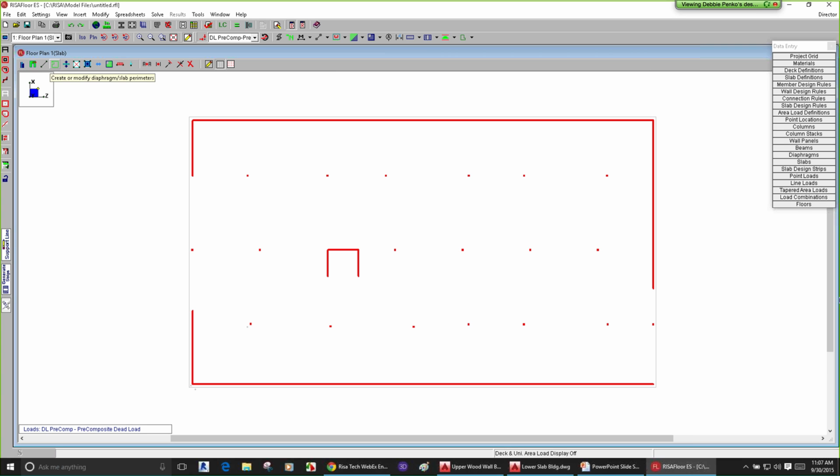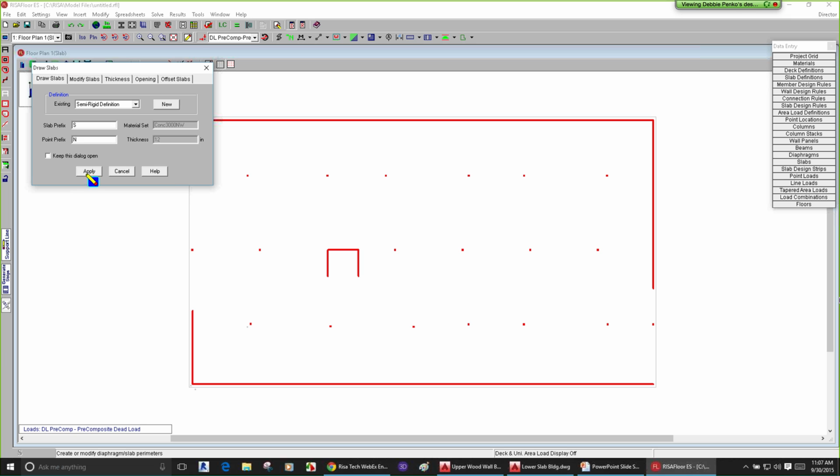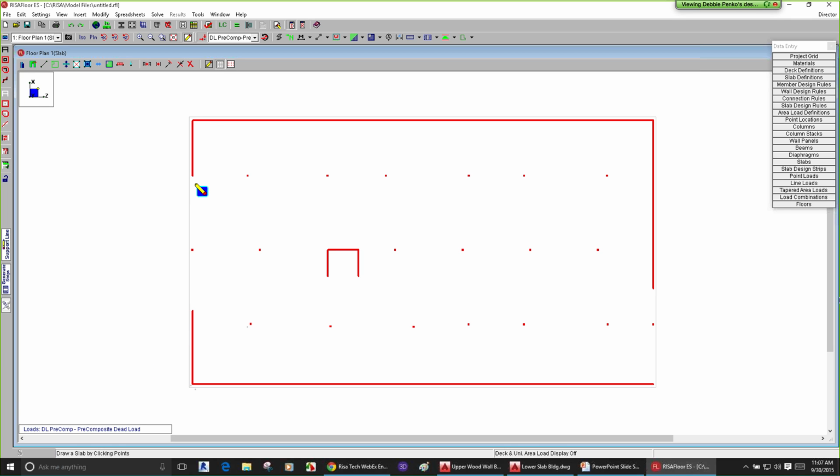So I'm going to go ahead and draw that slab semi-rigid diaphragm here in. And I just go draw. I can just trace what I have for DXF all the way around the structure. So we've got that in place here, and you'll see that green outline that shows me that slab edge. I could have made any type of shape. This happened to work nice for my podium, but if I had any other type of concrete structure where I had any edge, it doesn't have to follow your framing. It can be a cantilever of any sort, things like that.